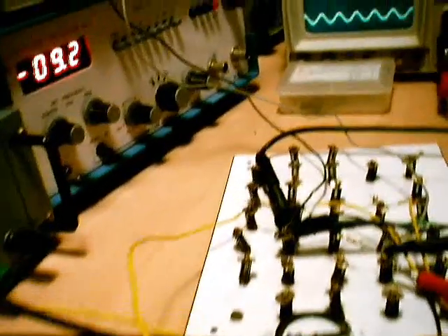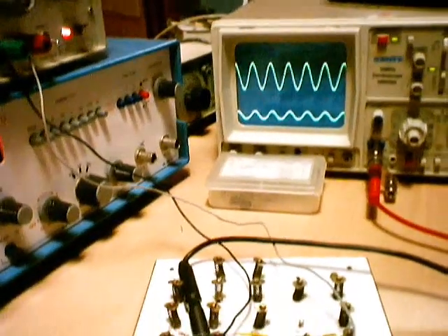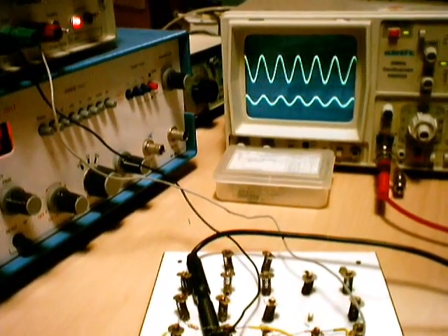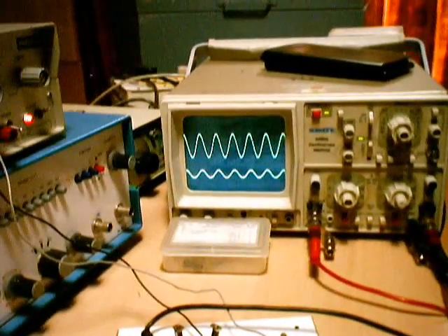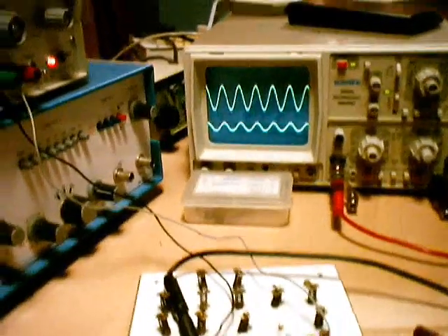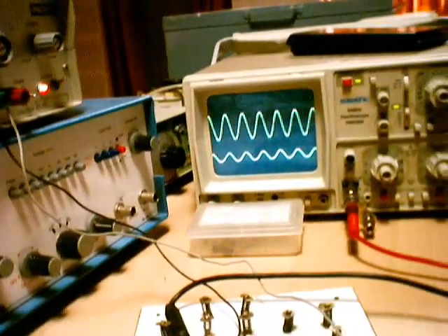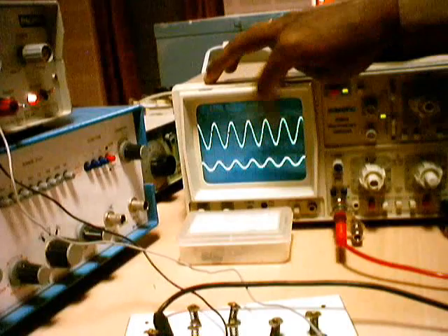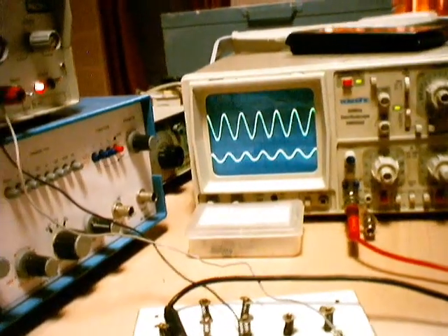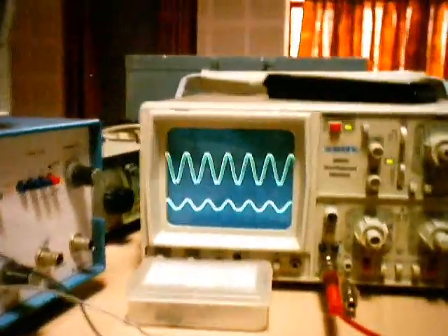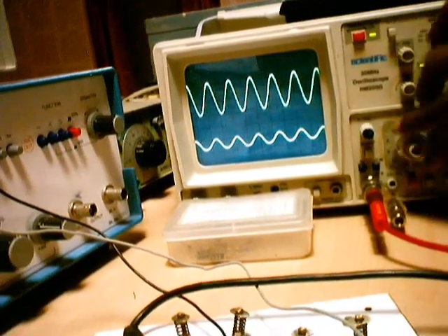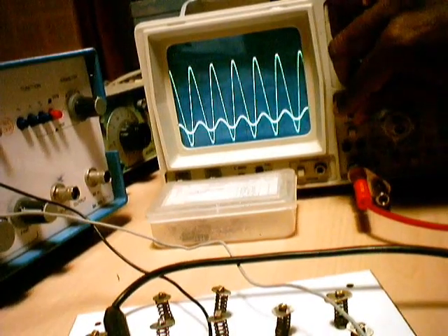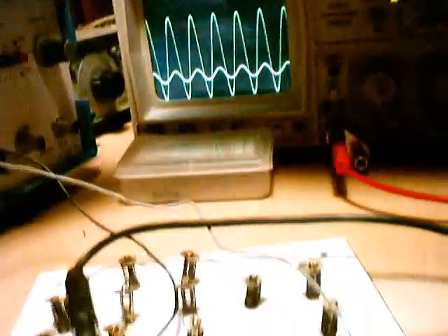Now I'll show the working of that one. Since we are using a voltage follower whose gain happens to be 1, we can keep the input voltage at any value. It's unlike your narrow band pass filter, where the gain was 10 and we had to keep the input voltage around 2 volts. Here it can be any voltage because the gain is just 1. Let me keep it around 10 volts.